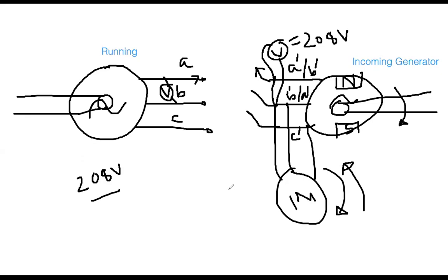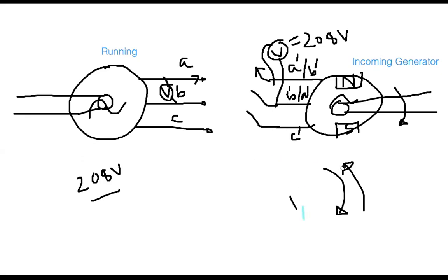Now, as I told you, you will be doing this experiment. This is, I think, lab number 6, connecting two generators in parallel, or synchronizing them. You will be doing this lab in the laboratory. What you will be doing, instead of starting an induction motor, is using a lamp system. I am deleting these things. It is called the synchronizing lamp. Let me write down the terminology. Synchronizing lamp. This means that with the help of the lamp, you can test the phase sequence.